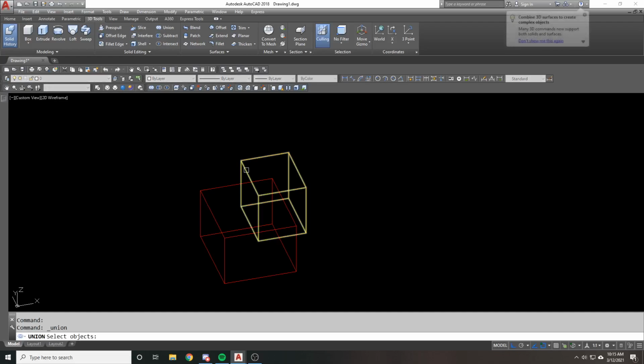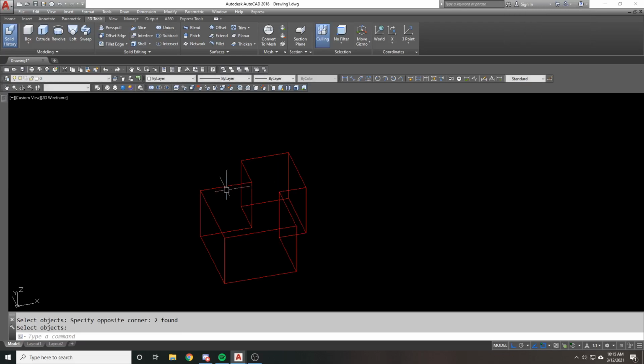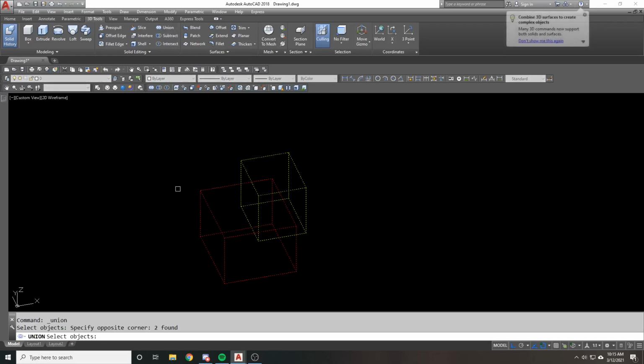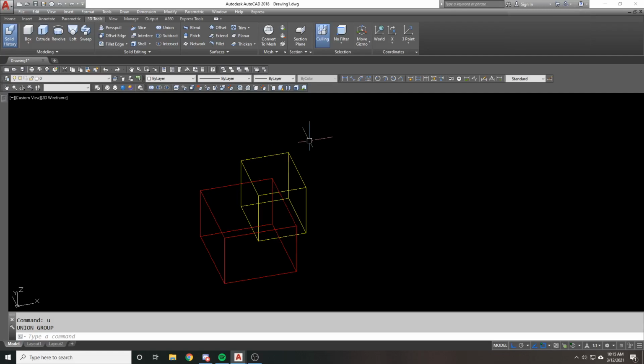We'll go the opposite direction. If I want this one to be first and then this one, it takes that layer. When selecting both, it takes the original object. Okay? Kind of like the one that's older in the draw order. So just kind of keep that in mind, because when you're unioning objects that have different layers, it's going to assume one of the layers.